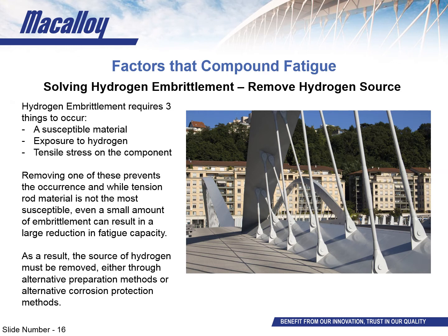As a result, you do need to address it and minimize any chance of it. And the usual solution for this is to remove any process that introduces hydrogen into the bar. Now, while it is possible to galvanize without the pickling process, it tends to be expensive, difficult, and the outcome is rather inconsistent. So the best way to go about it is to find another corrosion protection method, such as painting or other coatings of the material such as metal spraying.